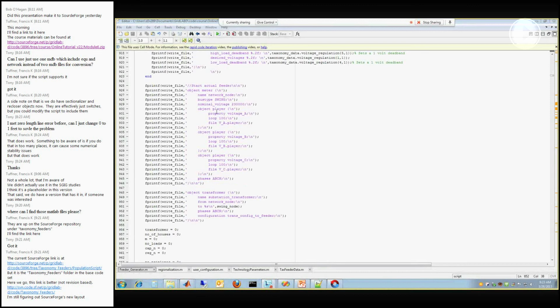Basically, that had a year-long set of data that we captured the voltage off of, converted back to sub-transmission voltage levels, in this case 230 kV, and used that as a player file to be representative of what the voltage variation might be at a substation. Note that's completely different depending on where you are and who you're working with, but for our basic model, this is what we used. We did things like clean it up and made sure that there were no voltage dropouts, but effectively we're just playing that in.